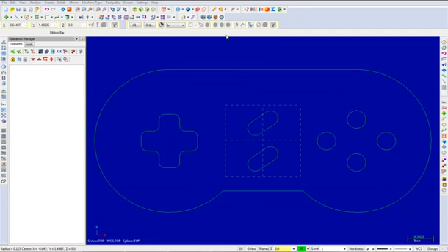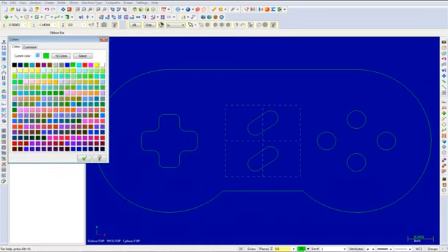From here we will change the attributes. Specifically, in this step we will change the system color and level which the solid will be created on. This will be done to allow us to view our part easier. Left-click on System Color in the status bar. When the color dialog box appears, choose color number 12 or the color red. Once complete, select the OK button to exit the color dialog box.